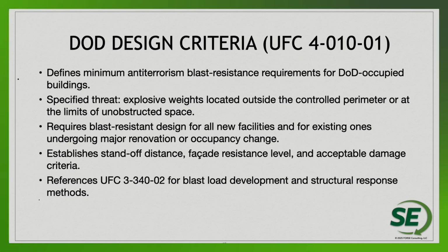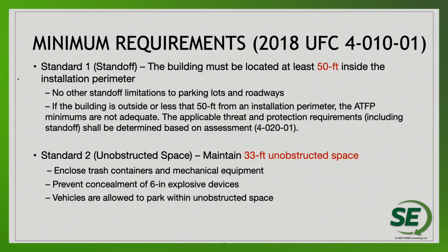Like I mentioned, this standard requires every new DoD building and of course any existing building undergoing any major repairs or renovation to be designed to resist a specified explosive threat. Only reinforced CMU meeting TMS 402-602 is acceptable for exterior walls, but I'll cover that in more detail.